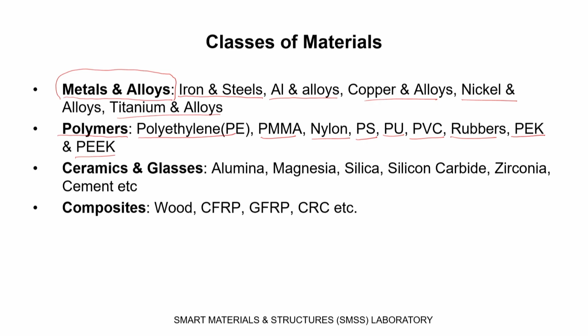And polymethyl methacrylate, let us take this one, it is also known as perspex. It has a very wide utilization. For example, we choose PMMA for dental fixtures. We also choose polymethyl methacrylate, as perspex, for different types of transparent system development. Polyvinyl chloride, you know it very well, is used for pipes, and that is something which can take many different shapes. By using certain plasticizers, you can give it different shapes. So, this is a powerful material. So, considering all these things together is our group of polymers.